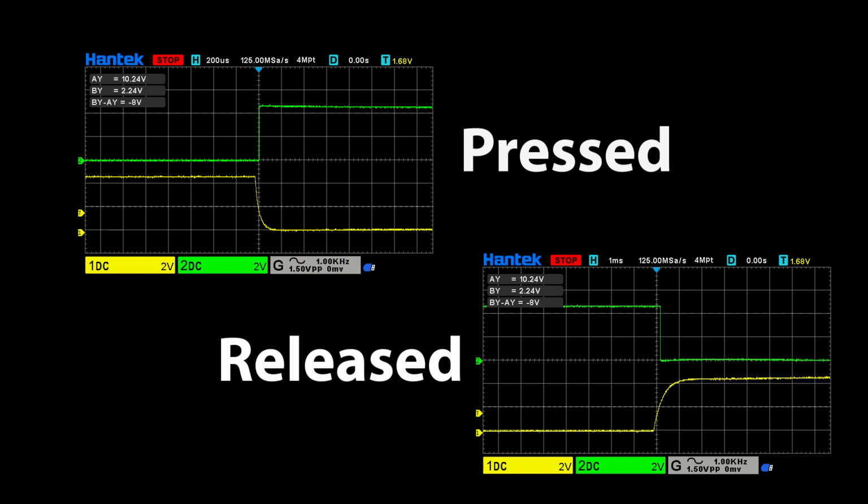Now for this circuit the Schmitt trigger really isn't required, but I've just included it for your reference. It sometimes is very useful to be able to clean up a slow rising edge or a slow falling edge to convert it into a cleaner digital signal.